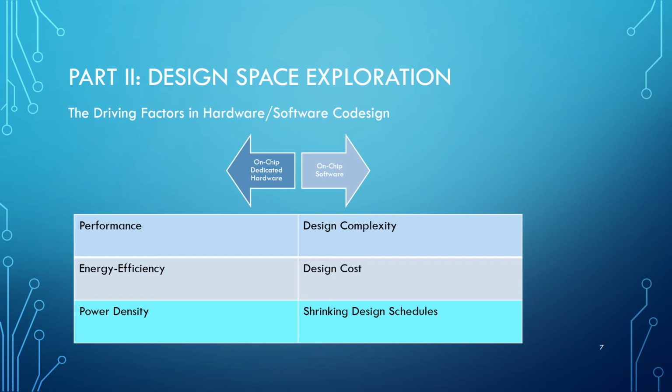The third part in favor of the hardware is the power density. The power dissipation of a circuit and the associated thermal profile is directly proportional to its clock frequency. In modern processors, the power density is at the limits of cost-effective cooling technology. Further improvement of performance can therefore not be achieved by increasing the clock frequency even more. Instead, there is a broad and fundamental shift occurring towards parallel computer architectures. At this moment, there is no dominant parallel computer architecture that has been demonstrated to be effective for all applications.